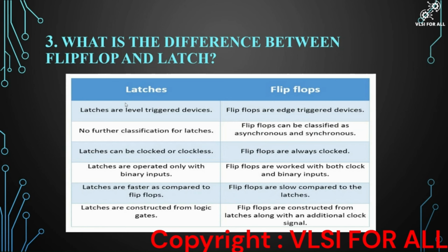Latches are constructed from logic gates, and these latches are further improved to build a flip-flop. Further improved means a clock signal can be added to the latch circuit to make it behave as a flip-flop. Do you have any other differences? Yes, we can write drawbacks also. Does latch have any drawback? Yeah, they have. That's why we go to flip-flop. What's the drawback of the latch? Latches are responsive to any faults occurring on the enable pin, whereas flip-flops stay strong against any fault.